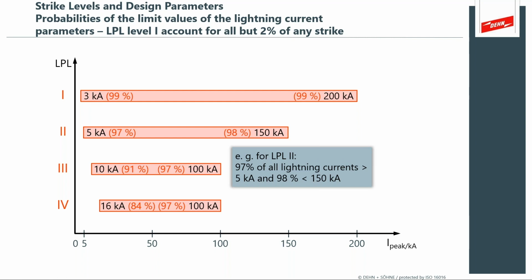So when you want to control the risk at your hospital full of babies and oxygen, a fire hazard, you want a smaller rolling sphere radius to get all the nooks and crannies that could occur from a small population of lightning strikes. If you have a less dangerous atmosphere and less population, easy to evacuate structures with a small number of occupants, you can use a lower risk level, because you can easily control your risk of fire then.